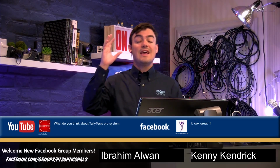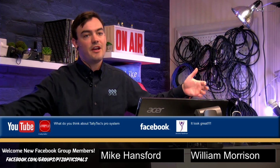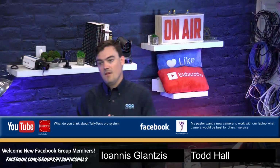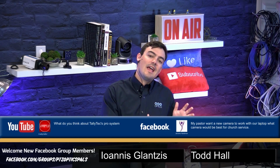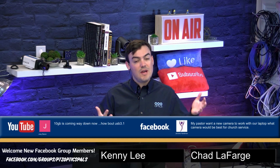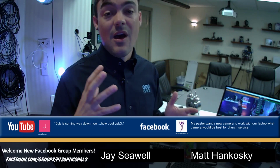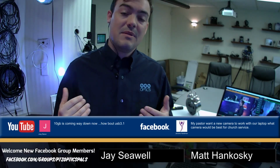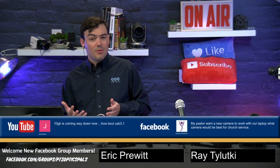One of the things we have to remember is SDI is uncompressed, okay? 3 gigabits of uncompressed video versus NDI HX, which is 10 megabits. It's very compressed compared to SDI, yet you can hardly notice the difference because of how well NDI has been built, and the send and receive is so smooth that you can't tell the difference.